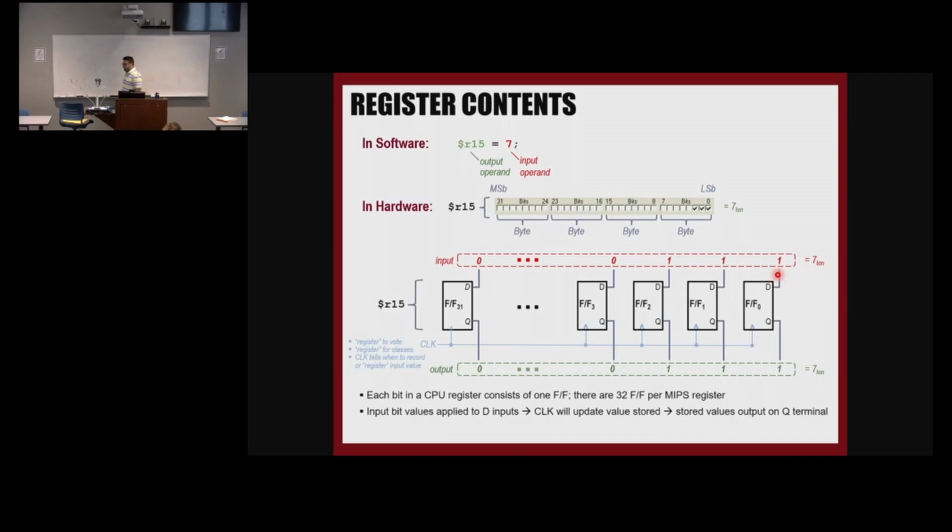So flip-flops are a kind of memory, you can call it a memory cell, that works with a clock. And in one clock, you can read from it and also store something in it. So in the same clock cycle, you can read what was stored in it and store what you want to store in it in the same clock cycle. And it's a pretty fast design. It involves transmission gates, there are different types of flip-flops of course, but every bit in a register is stored in a flip-flop. It's a pretty fast memory cell, but it's a large one.